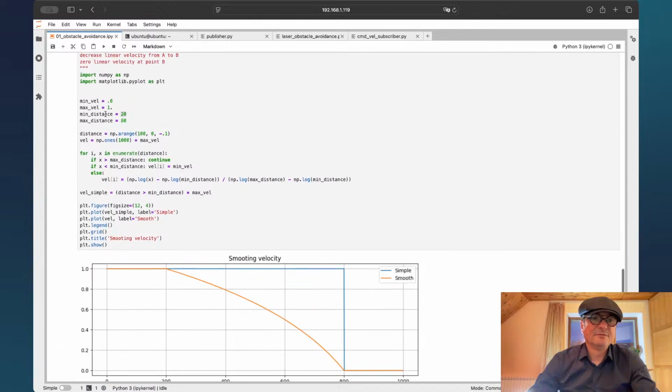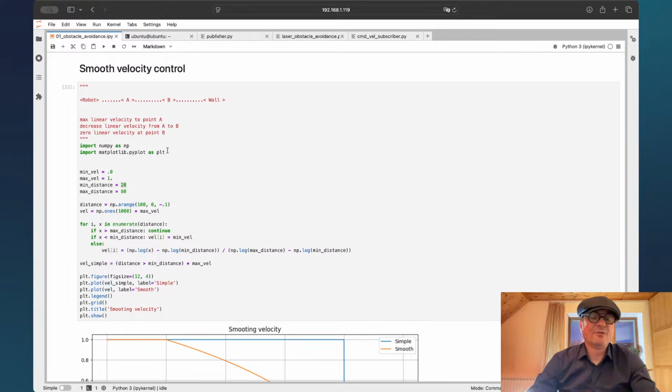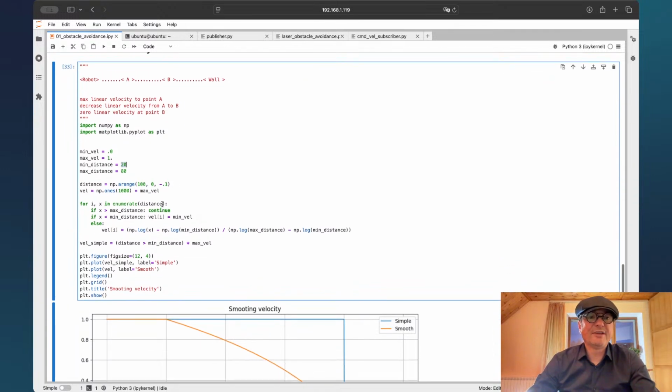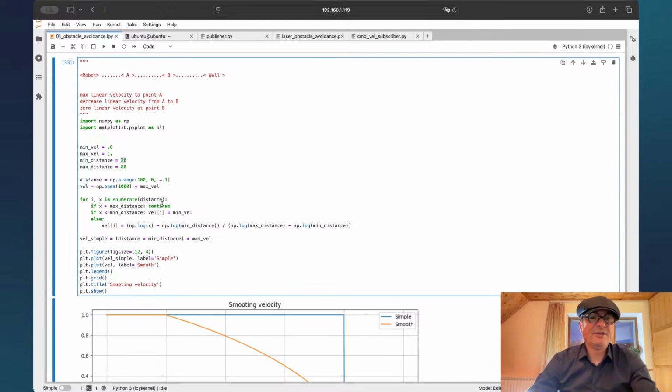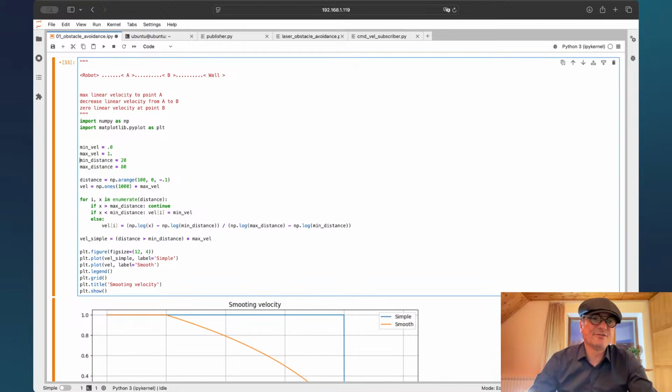For example, if you implement your obstacle avoidance algorithm and set the minimal distance to the obstacle to 20 centimeters, it could be okay for your simulator, but on the real robot this distance could be a bit small, and it couldn't stop because it has its own inertia, so you should increase your distance.